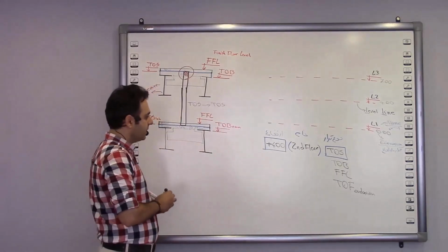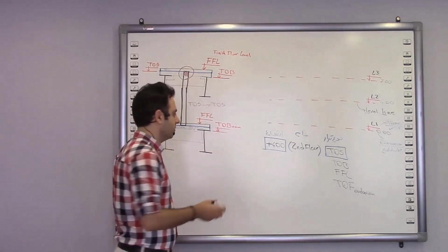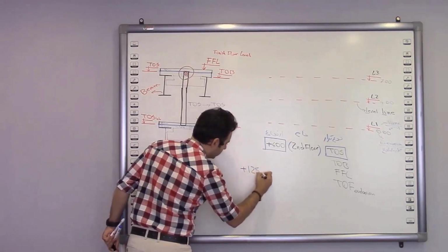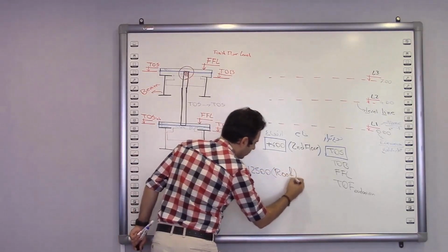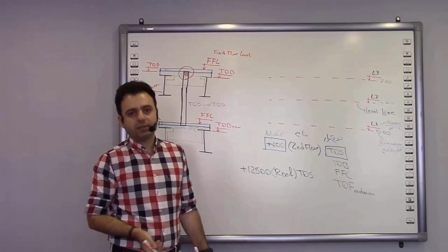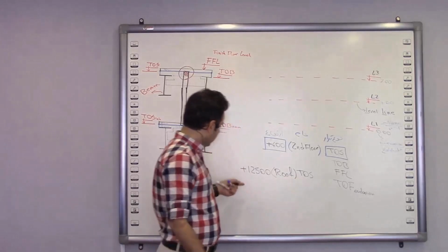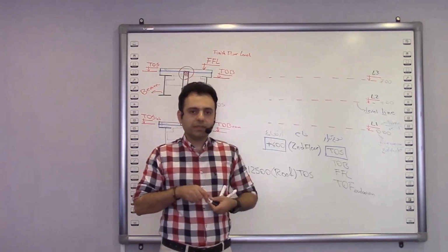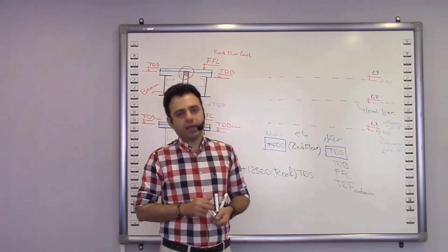Alright, let me tell you one more example. Maybe what floor? Maybe the rooftop. So, what is the height? For example, plus 12,500. We also write roof. The kind of the level, TOS. And we will use FFL too, but later, not now. When we want to design the floor, it's the same thing, but instead of TOS, it's FFL. Now, let's go and see all these in the software and start a multiple floor project to draw and practice.